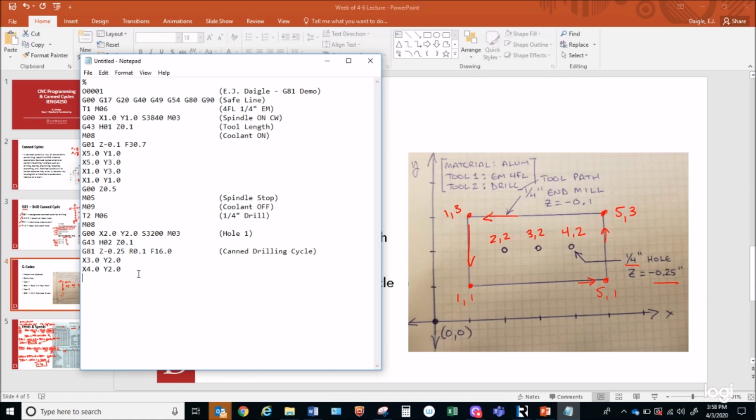You haven't had to call Z again. You haven't had to change speeds and feeds. And for that matter, I could keep going. I could just list a whole sequence of holes. I could put a dozen, I could put 20 holes. And I could just drill them all with that canned drilling cycle.